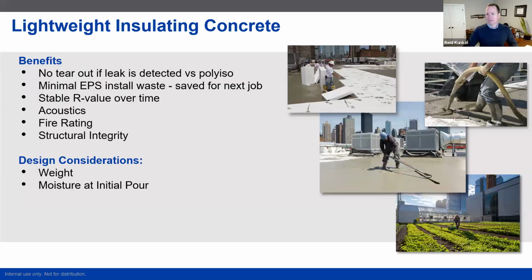Hey, Rick, there's a question about mineral wool. Is mineral wool utilized? Yeah, so in the vegetated roof world, we use a mineral wool. Most commonly, it's a needle punch product, and we'll talk about it. In terms of insulation, I'm most familiar with rock wool as a board that has a binder in it. And so from that perspective, I think it's most commonly used in wall applications, not horizontally on the roof. But certainly another type of insulation that's common in the marketplace and utilized within the building envelope.